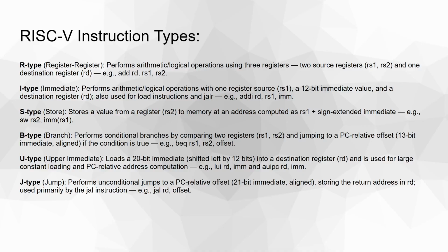You can always keep the reset high. There's a lot of different ways that you can keep it zero in hardware, but you need the zero register to remain zero because when you initialize your program, you don't know what's in all the registers. You can reset them sometimes, sometimes you can't. So just having that zero register makes it possible to set your register values to zero.